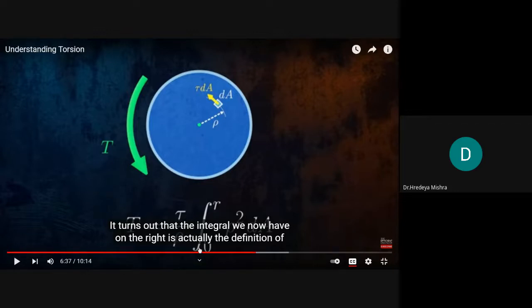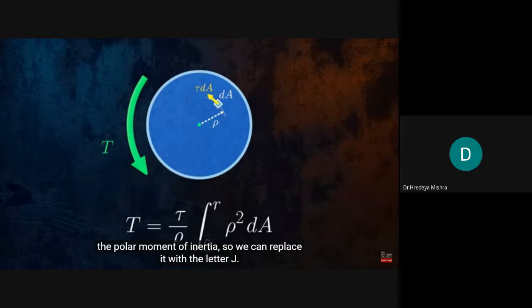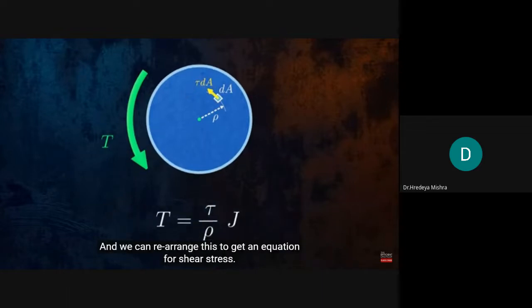Okay, tau upon rho is the constant for the equation, so we can remove the tau upon rho from the integration. It turns out that the integral we now have on the right is actually the definition of the polar moment of inertia. So we can replace it with the letter J, and we can rearrange this to get an equation for shear stress.